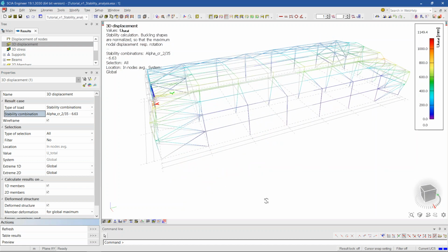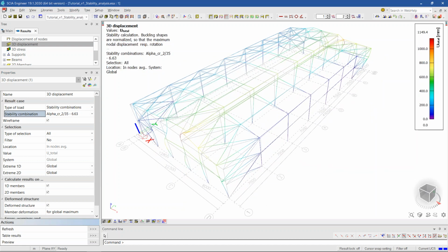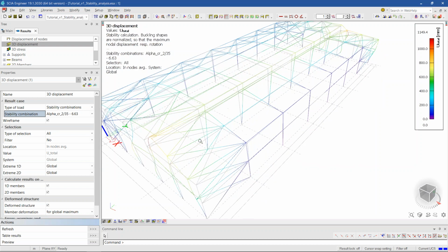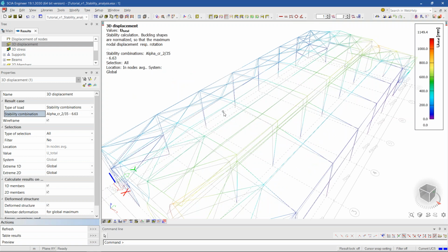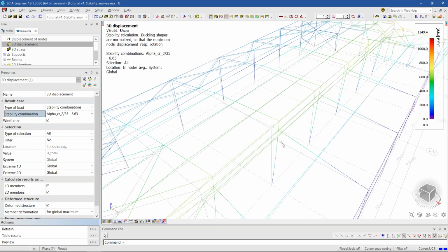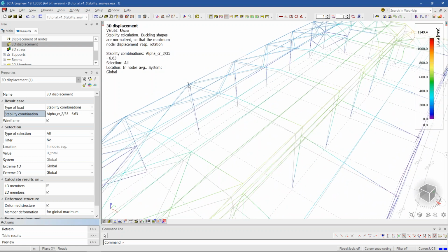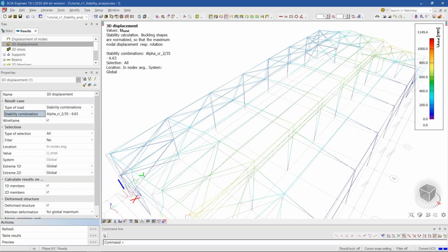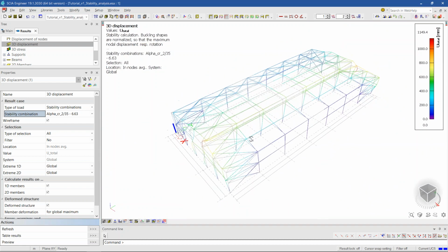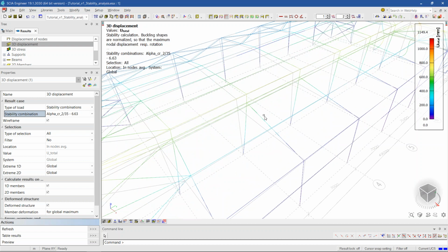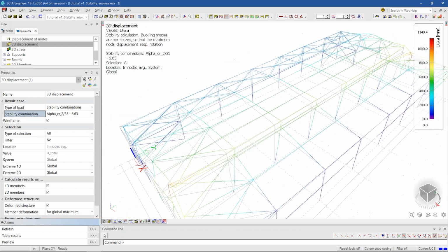And so we see that we have a problem with our structure, and I will tell you why this is a problem. For one reason, if this structure was moving in the other direction, we have rigid connections, and we can just tell SCIA, well, calculate the factor based on the formula for the sway mode, and then we are done. Then we don't have to do anything. But in this case, we have hinges, and then the calculated factors will also not be okay.